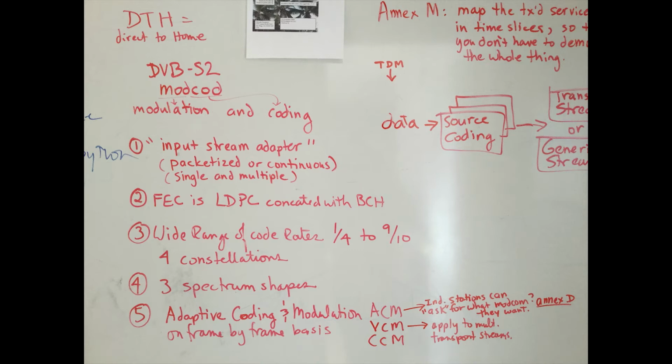5. This standard lets us learn and develop with something very much like cognitive radio. As you can see, there are a lot of choices for coding and modulation, lots of different combinations. We can specify a fixed coding and modulation. This is called CCM, for constant coding and modulation. In the past, people like us would look at a link, design for the worst case solution, and use coding and modulation that would cover all these bases.